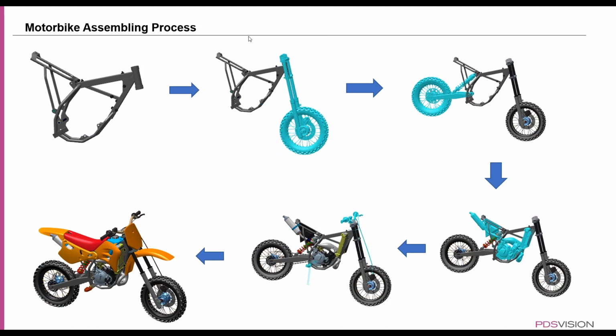And on this particular operation as well, we can assign the resource to it. I can say I need an assembler on here, and I also need an assistant to assist this assembler. Obviously they will need tools as well, screwdrivers and stuff like that. I can also assign those tools on this operation here. Same for the different operations.